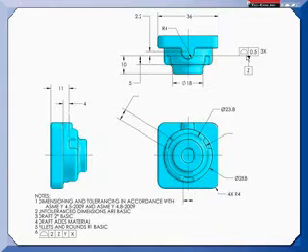So our primary datum feature is these 3 surfaces that the tops of the jaws will touch on. So these 3 that we see here. And we made that datum feature Z. Then this diameter, it's made up of those 3 surfaces. We've made Y.